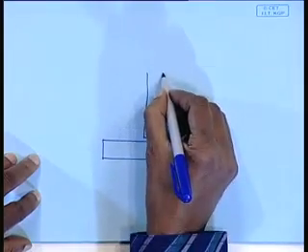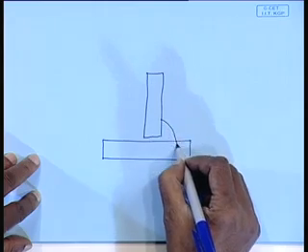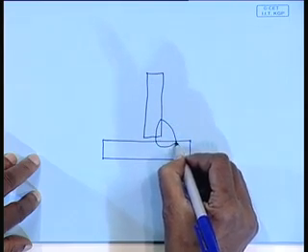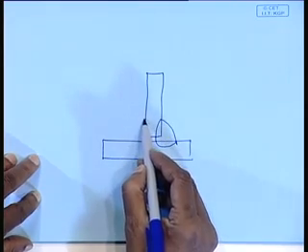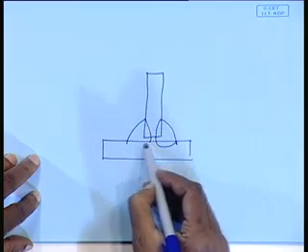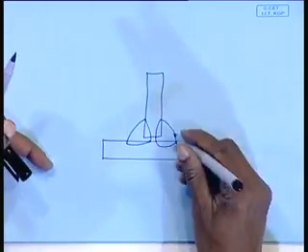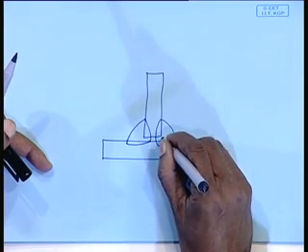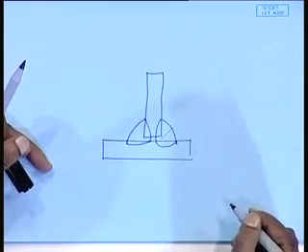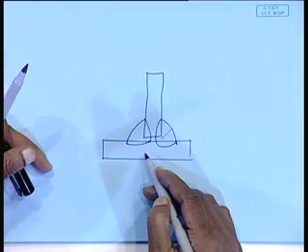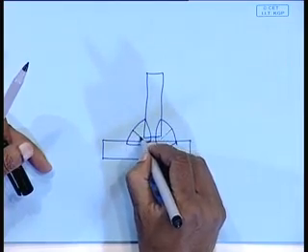In fact, just the other day I was telling you in the previous class, a simple case of fillet welding we had been doing, with a submerged arc, the fillet was like this, both sides fillet, and a crack was observed right in the center line, through and through crack, from the surface till inside.